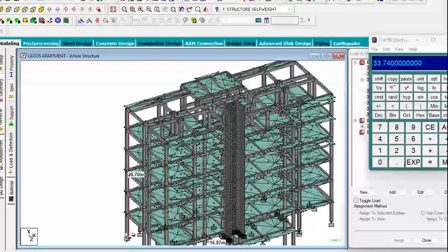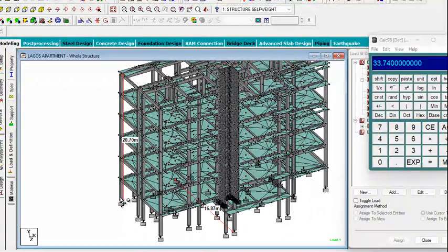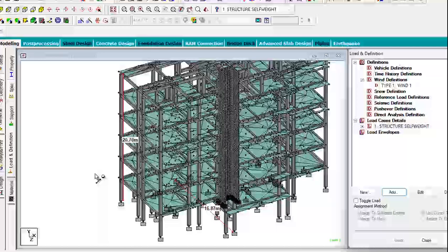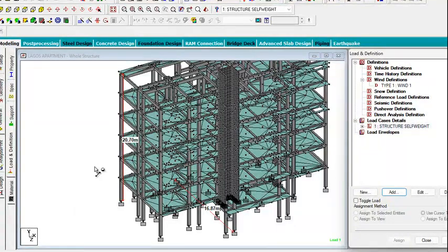Therefore, you're going to calculate wind pressures at two governing elevations. The first elevation is 16.87, and the second elevation is 20.7 minus 16.87. So you're going to calculate the wind dynamic pressures at these two elevations in this direction. It's those two elevations that you're going to consider in the analysis of this structure. Thank you.